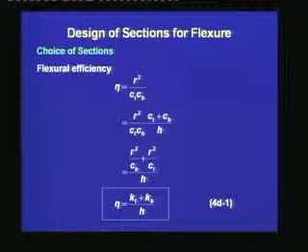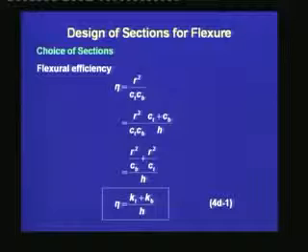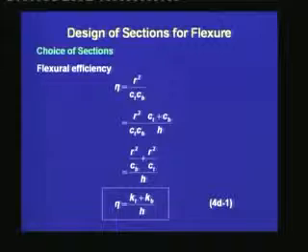It is defined as eta is equal to r square divided by Ct Cb, where Ct is the distance of the top from the CGC and Cb is the distance of the bottom from the CGC. To this expression, we are multiplying a factor Ct plus Cb divided by h.